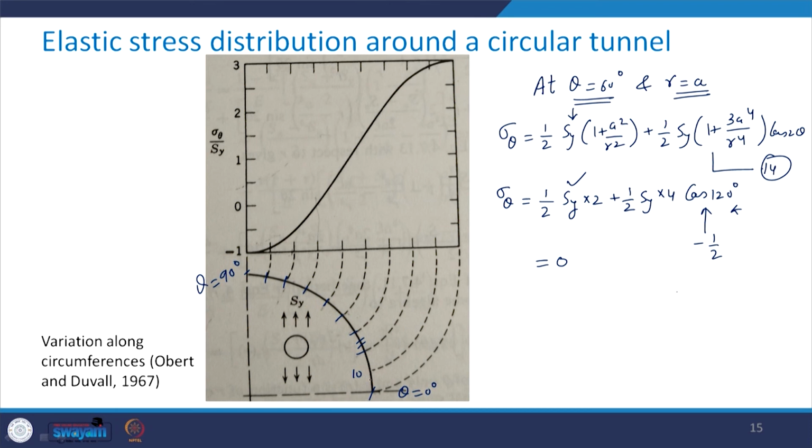Now, take a look here at 10, 20, 30, 40, 50 and 60. We just take its projection like this and then go across, and here you have the stress concentration factor. Corresponding to theta equal to 60 degree, you have sigma theta equal to 0. That is how your curve is also giving you.